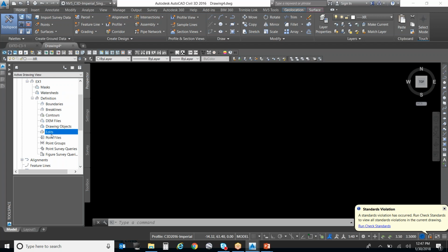The last two on here, point survey queries. We don't really want to use that. I've never used that in my career. Again, we want to use point groups so we know exactly what we're using. Same thing with figure survey queries. You should know what survey figures you want to use as break lines. Those are the only ones that you should import into this drawing, just the ones that you want to use. You can do that through your survey database. You can select what survey figures you want to import.